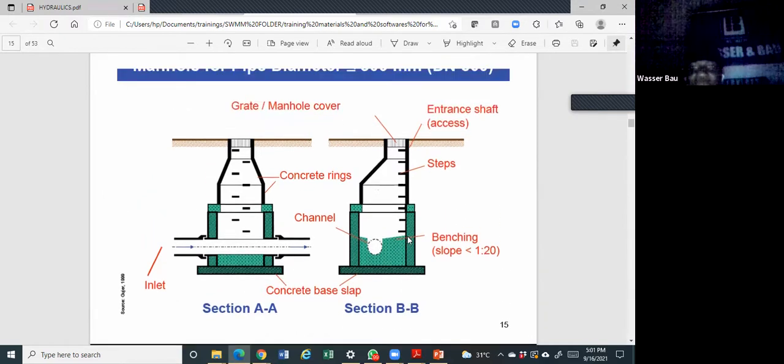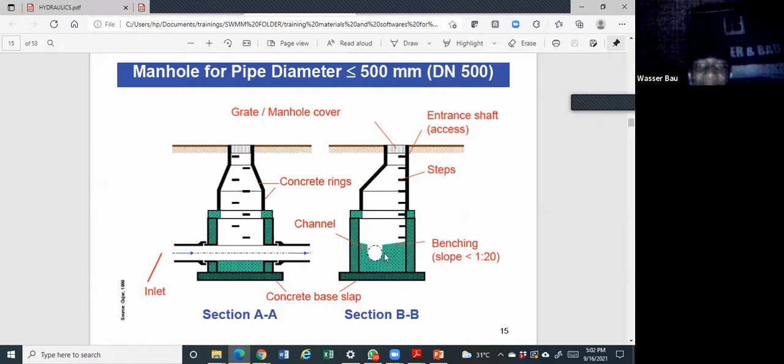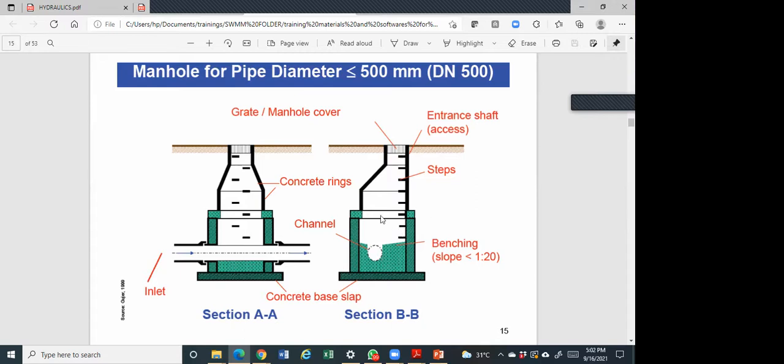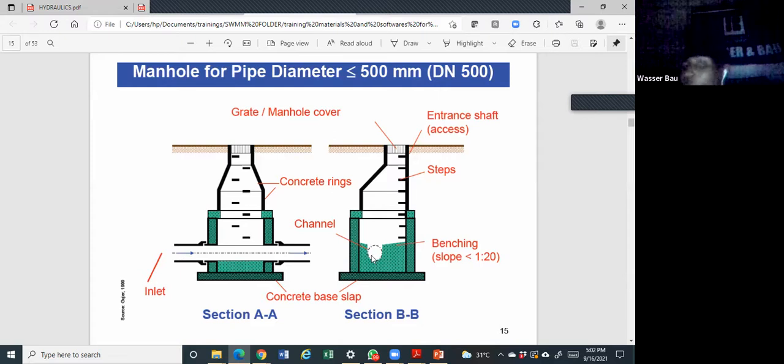All from here now is just giving you some definition of terms, just for you to understand. Engineer that asked me about the feasibility of combining both flows, I think what they do is something like this, but it's not completely this. It looks like this, but it's bigger in size. During dry weather flow, your sewage will flow through this orifice. Then during stormwater, the whole thing is filled up, while this one still continues to flow, but a bit diluted.